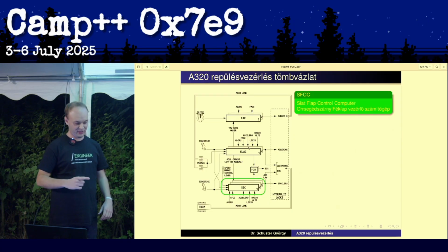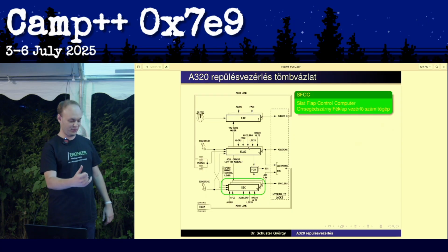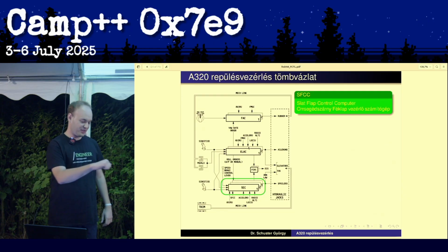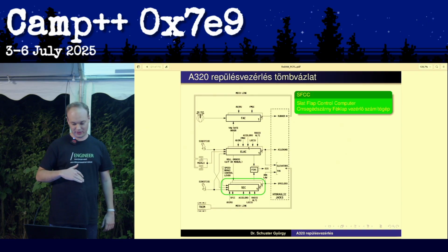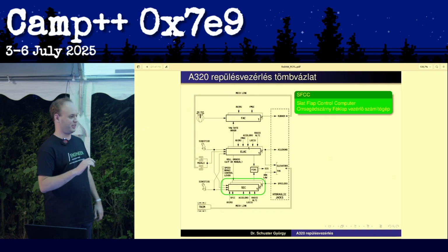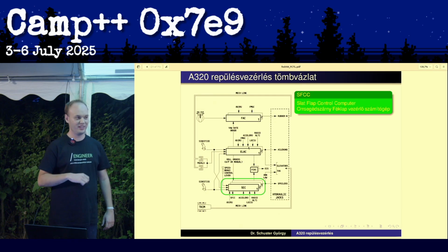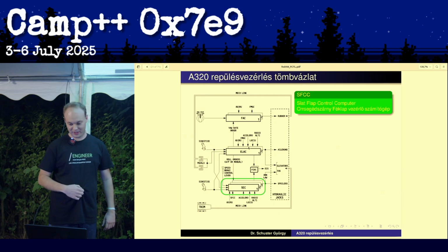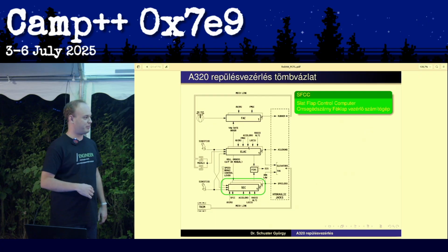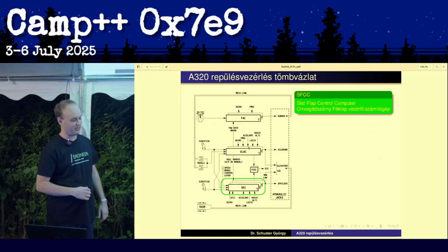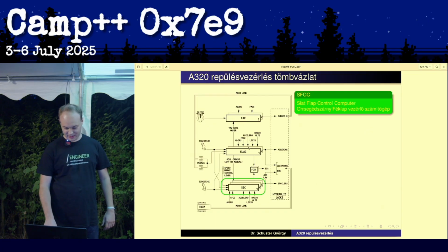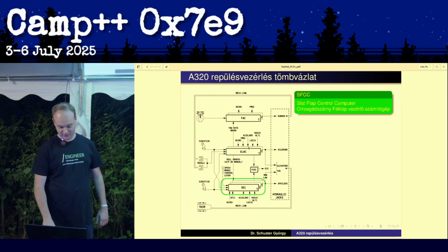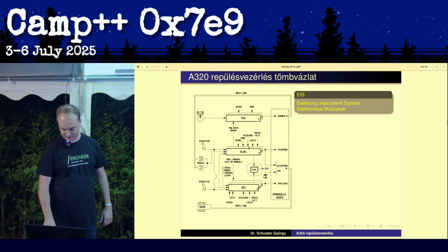The trim wheels have a little turn handle that you have to fold out and crank backwards, but it only adjusts the stabilizers by about half a degree for each turn. So it's not a fast process. And again, the pilots weren't ready for such a failure. So yeah, it led to several accidents.